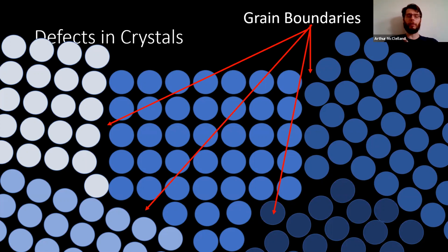The semiconductor industry has worked really hard for many years to make beautiful single crystal raw material. A silicon boule is like a 4-foot single crystal. Every atom is exactly where it should be. There's no polycrystallinity to it, because these grain boundaries are going to change the conduction. They're going to change the electrical properties. They're going to change the mechanical properties.